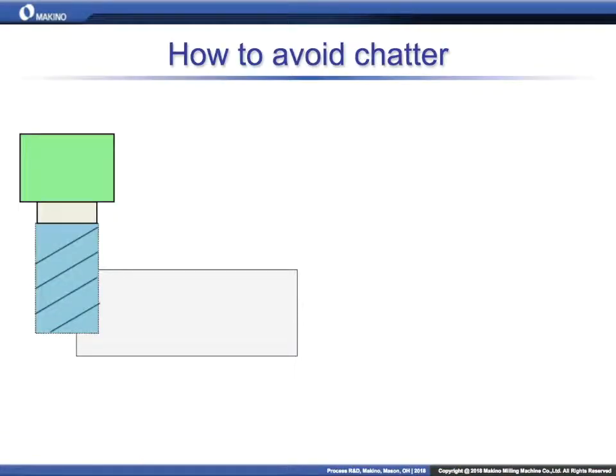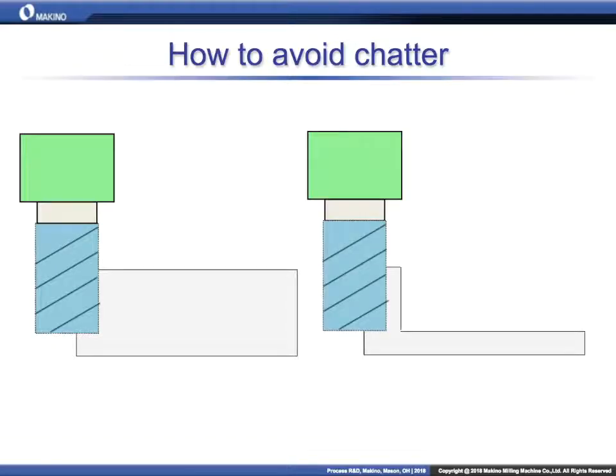we've really been focusing on chatter as it relates to the tool in a situation like this. So we've got this big heavy block, and we've got a tool, and we're saying, okay, you're hitting chatter, we're assuming it's the tool moving around. But when you create an extreme situation like this, where now we've got a very thin wall, if we were getting chatter in this situation, I would look at that and tell someone that, hey, the wall is moving. Right. So they're getting chatter from the part movement. Do they still do a tap test, or how do you still monkey with the RPM? How do you address that type of chatter situation?